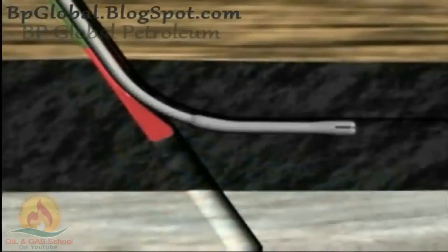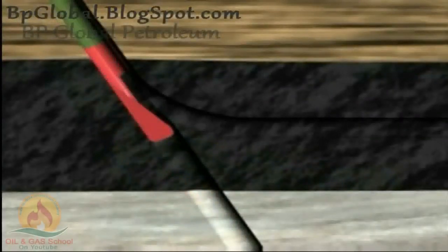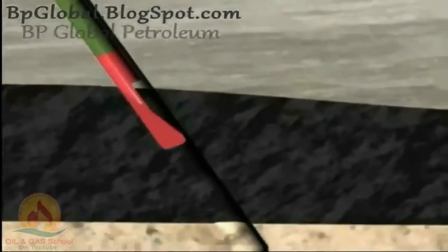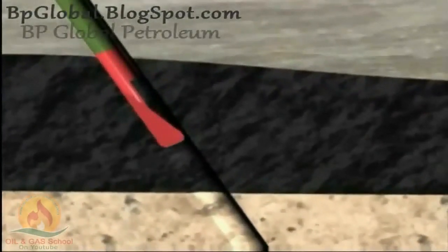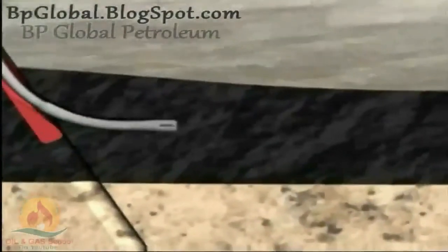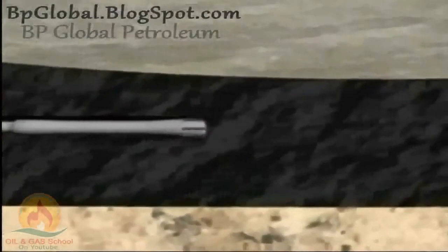Upon completion of drilling the first coal seam, the motor assembly is retrieved to surface, and the upstock is now ready to be moved to the second coal seam location. The upstock does not need to be retrieved. We simply add joints of casing to the carrier string, lower it to the next zone, and orient it. The process can be repeated for as many as 10 laterals without having to be retrieved.